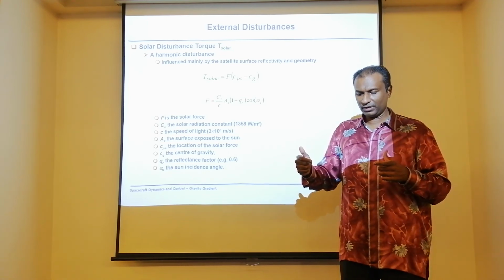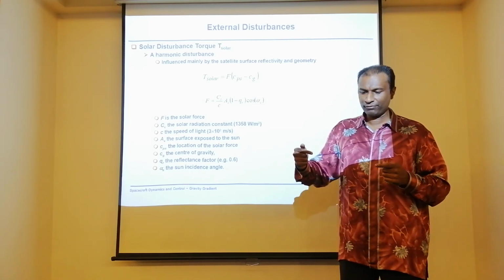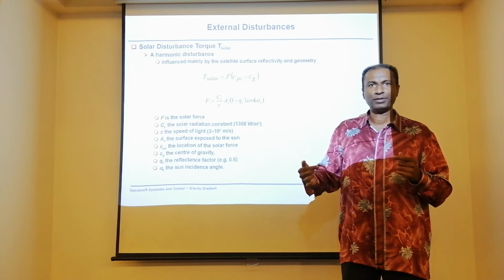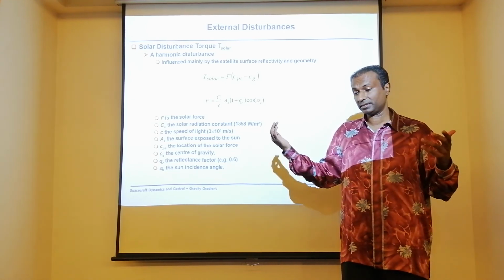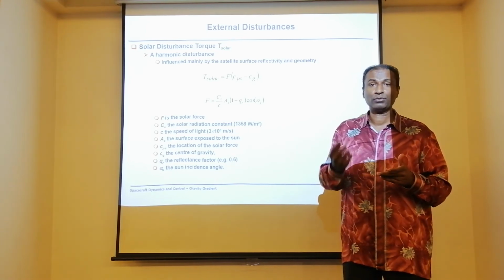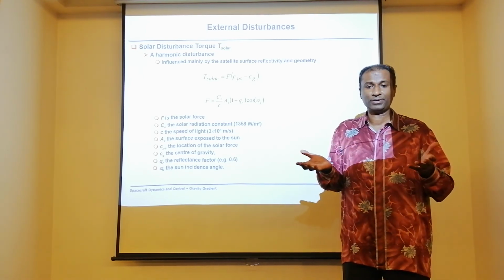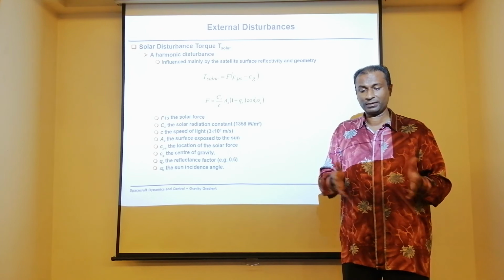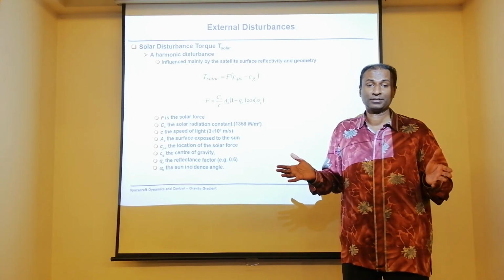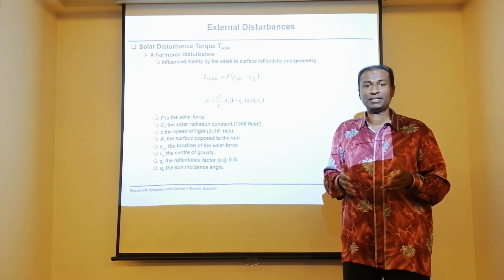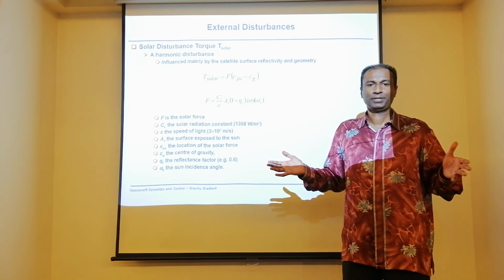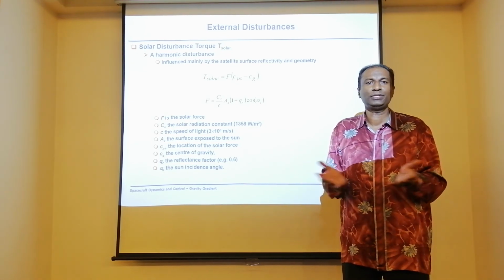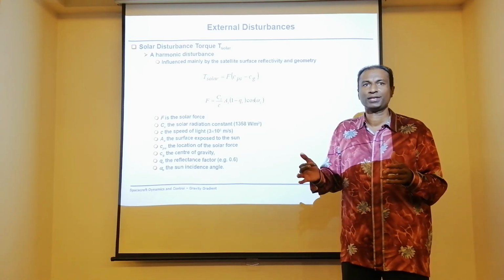If you're not careful about where you put the pressure point, you may lose. The disturbance can be acting on only one axis. Just like the example I gave, you can arrange the aerodynamic drag such that it is not affecting your pitch. Yes, but that is not the best model. You need to make sure that you give a worst case.